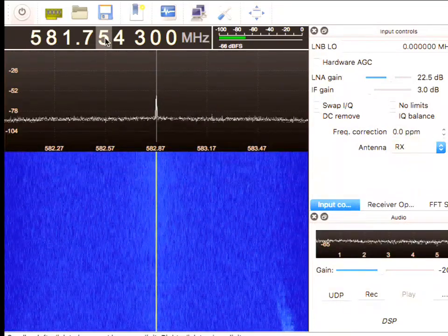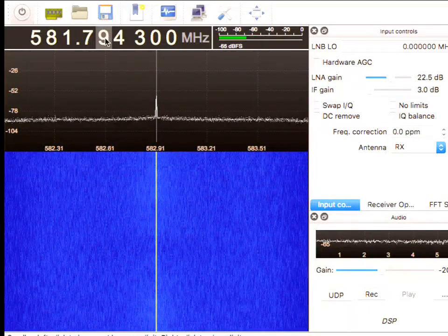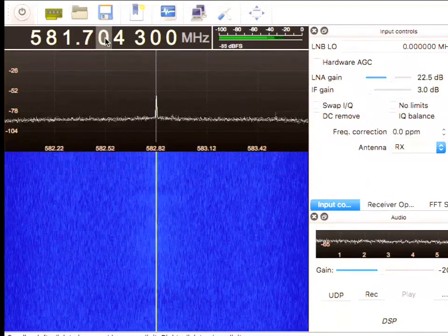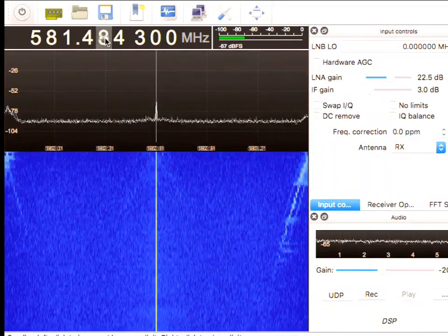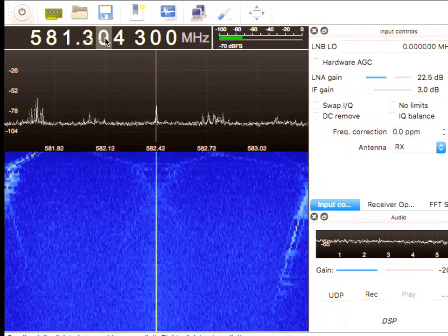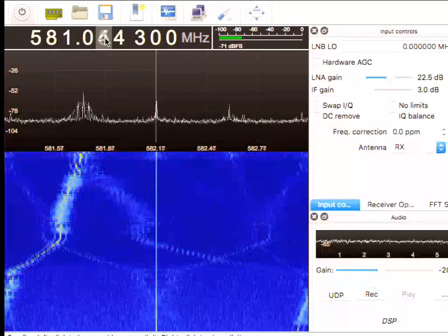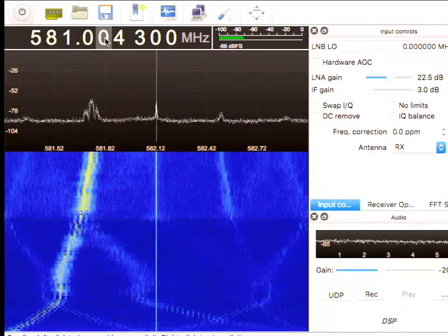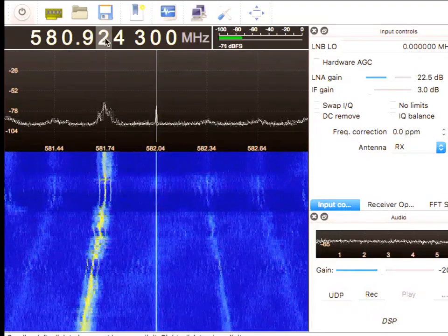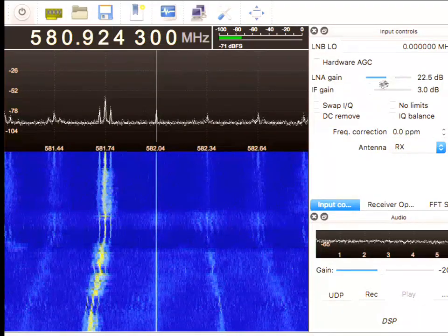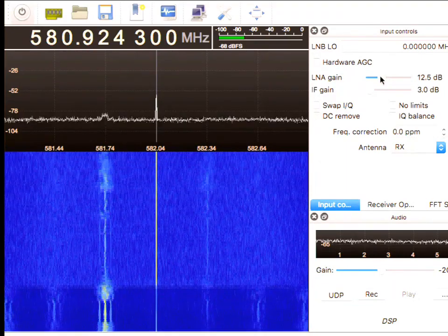Right? So effectively now you saw the roll-off of the anti-aliasing filter. Okay? So I'm going to move back. Oh, it comes up. And now it shows in the right place. Now, do you see all those things that are going the other way? These are all nonlinearities, what are called images, because of just the nonlinearity of the receiver here. I can actually reduce this a little bit. Okay, any questions? It's pretty cool, right?